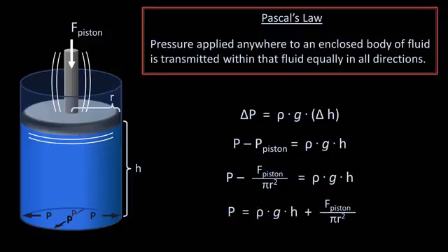You may not immediately realize it, but this solution depends upon the fluid being non-compressible, which we said was an assumption made for liquids in elementary fluid mechanics, though this would not hold true for gases. If the glass below the piston was filled with a compressible gas, the density of the gas would be a function of the pressure applied to it, and our solution would look a bit more complicated. But let's apply this general concept of a piston imparting a force on a non-compressible liquid in a somewhat more complex situation.